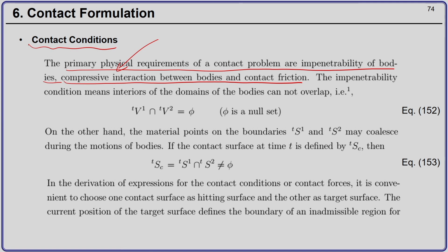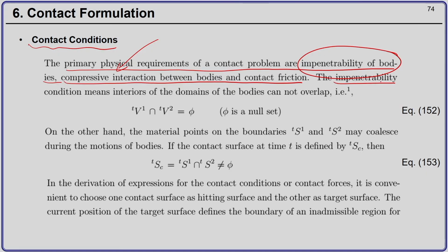If you go to adhesive contact problem, then there can be tensile tractions also. Now, this is one important thing. The other is impenetrability, which means that during the entire course of simulation or the contact, one body cannot penetrate the other body, that is physically not possible. So, the impenetrability condition means that the interiors of the domains of the two bodies cannot overlap.